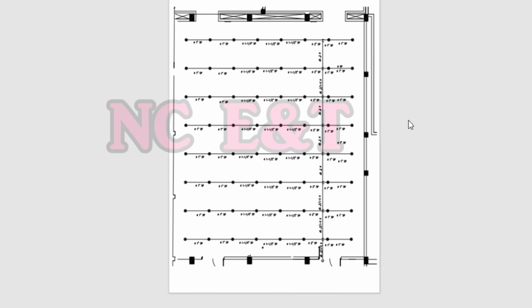Before this, we made the calculation for a remote area of 1500 square feet as recommended by NFPA, then we generalized this study to our project, made the construction lines accordingly, and located our sprinklers. Then, using the pipe schedule method of NFPA 13, we selected the pipe size.